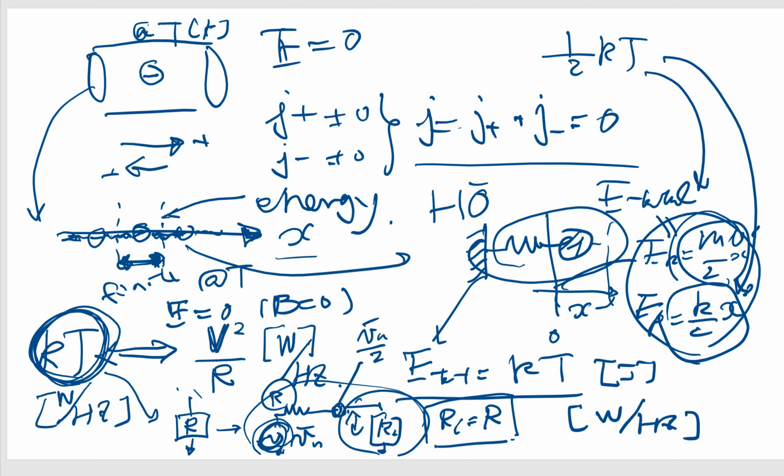and this voltage is Vn, but R divided by R plus R, so the value is half of Vn. So this V equals this V. External devices attached to the noise source catch the noise signal like this with this value, half Vn.